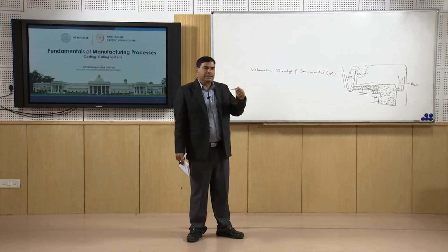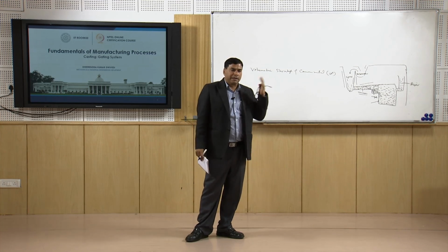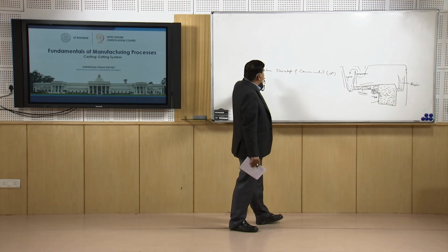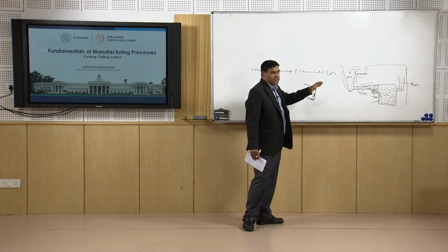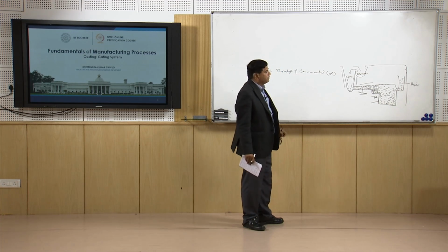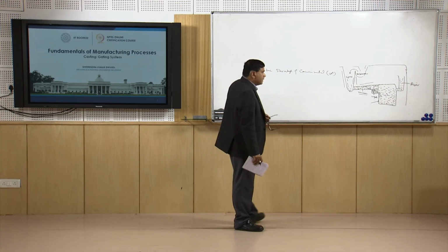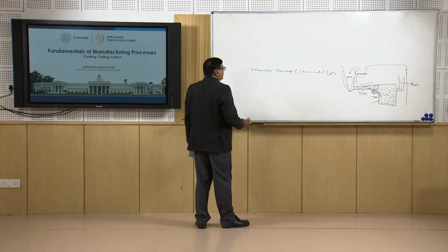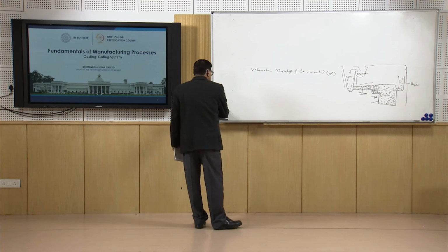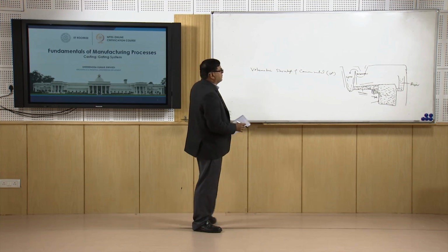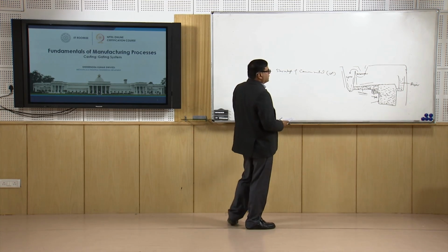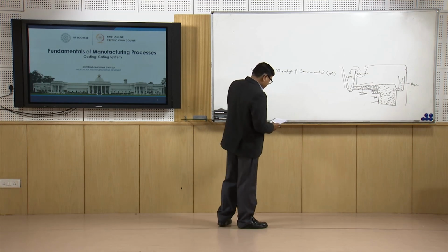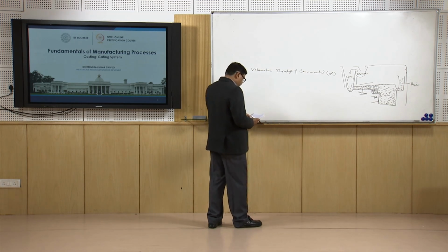We have considered the linear dimension for calculation of the shrinkage allowance, but here it is the volumetric shrinkage which will be considered for determining the volume of the metal in the riser, so that required liquid metal can be fed to deal with the shrinkage of the metal due to the liquid to solid state transformation in course of the solidification.